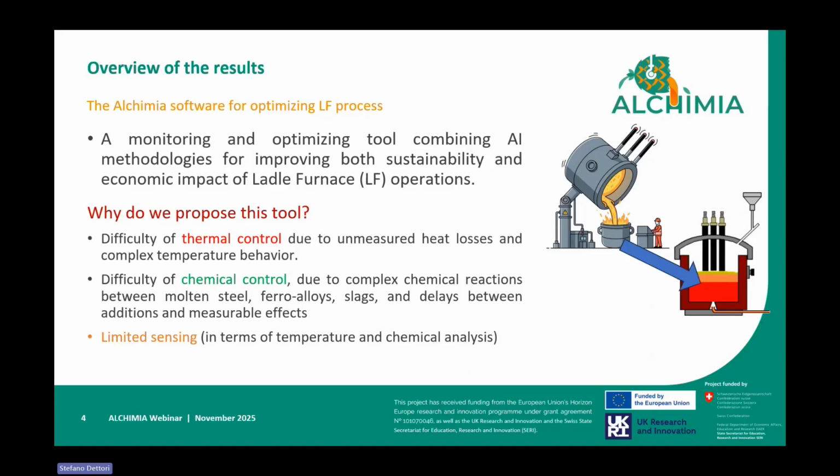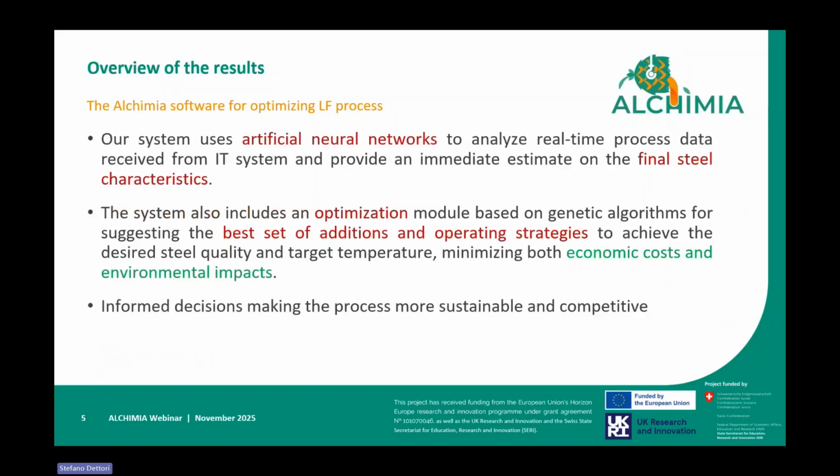But also in terms of chemical analysis, because the operators must take a sample of the molten steel, bring it to the laboratory, analyze it from a chemical point of view, and see what the current chemical composition of the steel is, in order to understand what kind of alloys, for example, to add to achieve a specific steel quality.